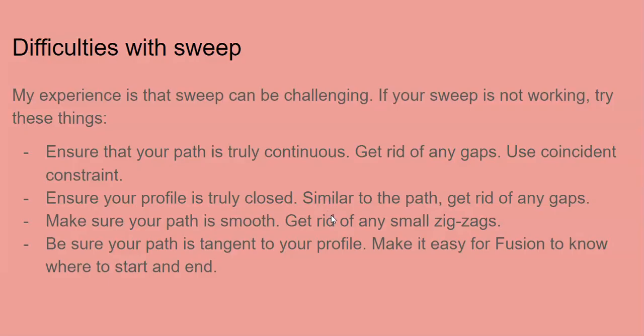Now, you may find that sweep is quite challenging, and I've been struggling with it myself. And if you find that your sweep is not working, or you're getting error messages from the software saying that it can't create the sweep, here are some things you can do to debug it. The first thing is to make sure that your path is truly continuous, and get rid of any gaps in the path. And similarly, ensure that you have a truly closed profile.